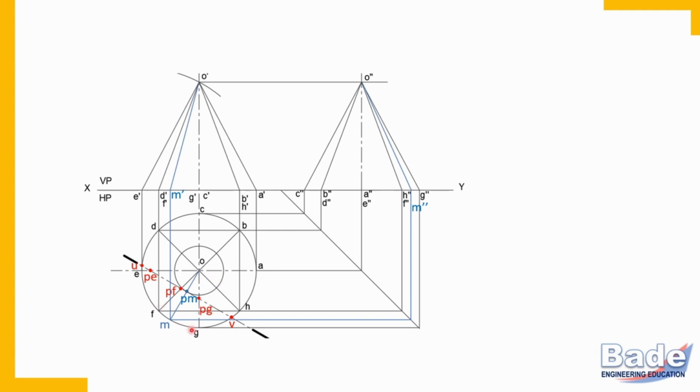Now the second important thing, listen to me very carefully. Sometimes it is possible that one of the earlier 8 generators is perpendicular to the cutting plane line. Have you understood? It is possible that there is already a generator available perpendicular to the cutting plane line. In that case, this extra generator is not required.